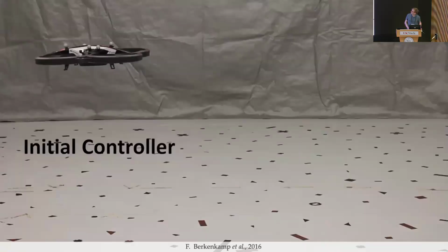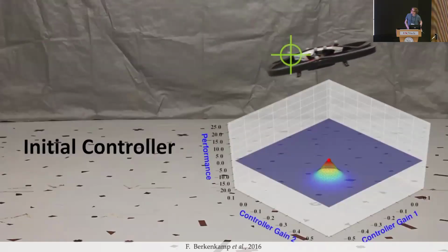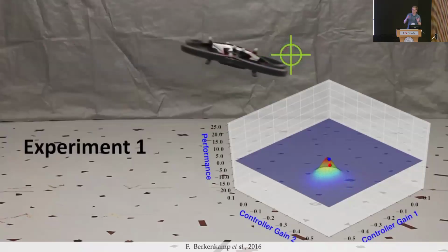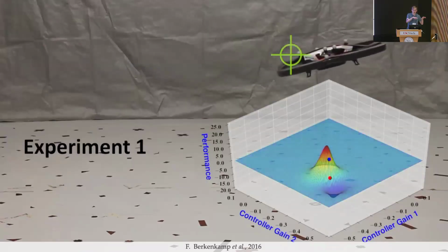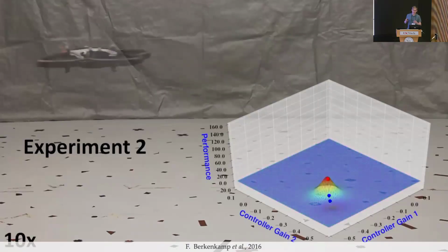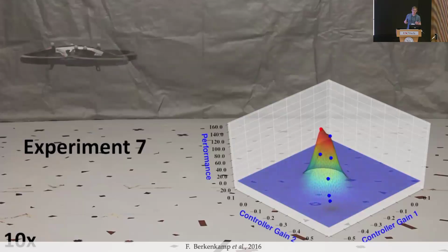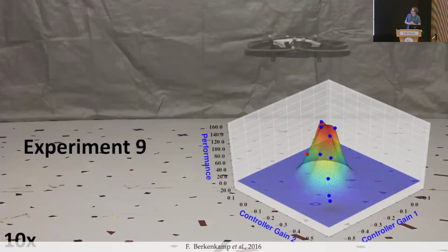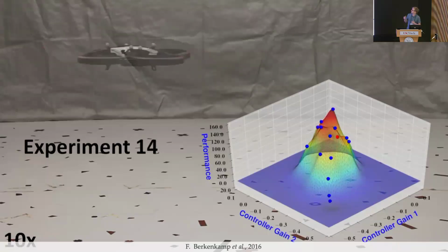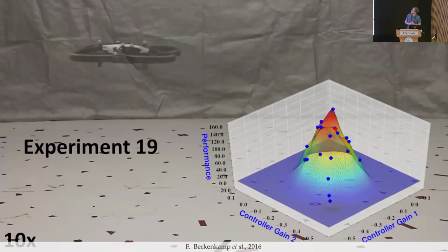So you have an initial controller that is not doing very well. But now you have this function where you map from the controller gains to the performance using this Gaussian process. And the safety constraint basically is to not do worse than before. You can sample new points using this safe optimization framework with constraints. And you can improve the performance of the system without getting worse. And so you can see that the performance is getting better.